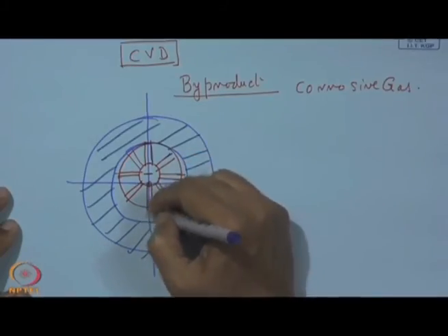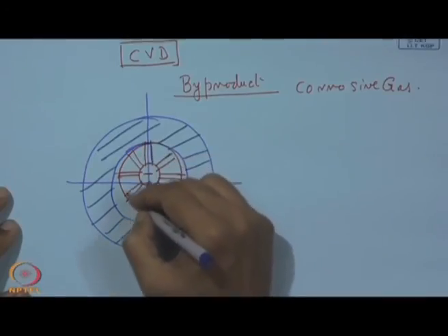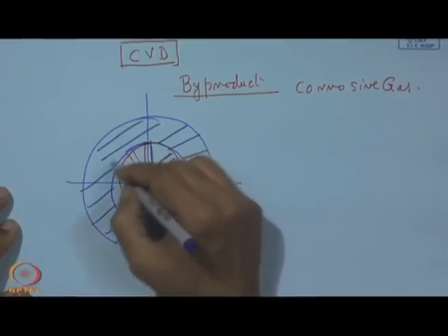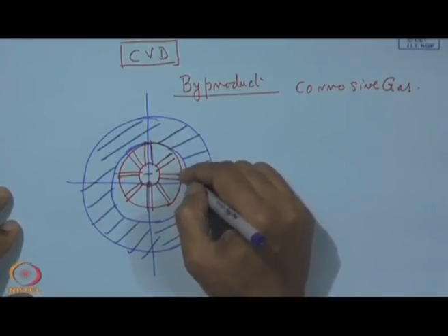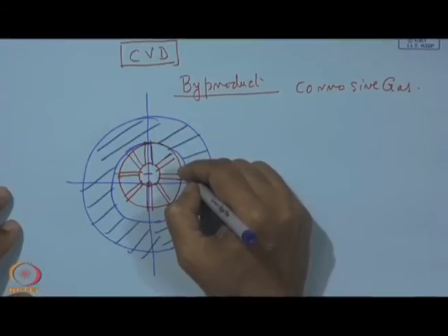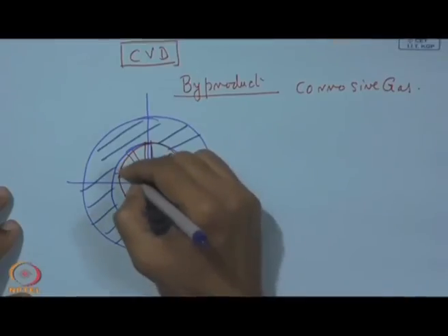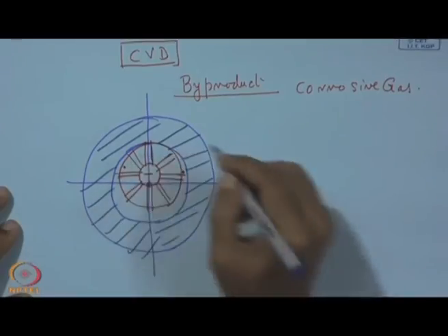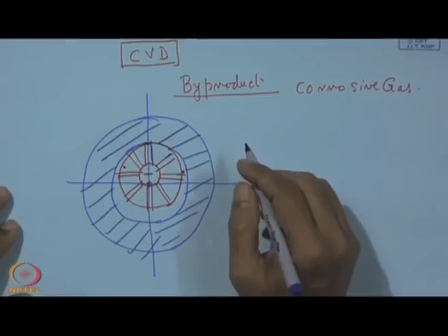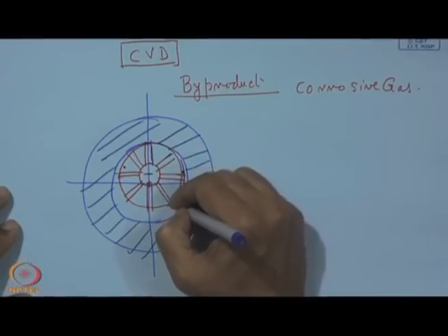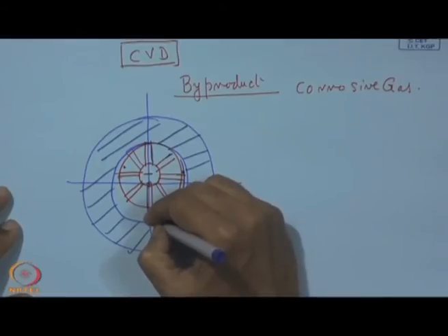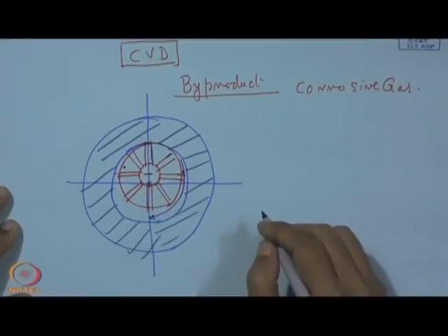There will be a gap between this rotor and this water ring. So, if we have some kind of admission point from this side and an exit point in this direction, we can see here that the volume is gradually changing and it is actually expanding on this side.